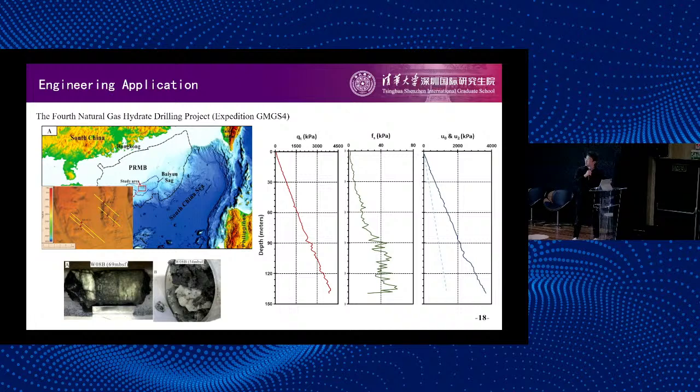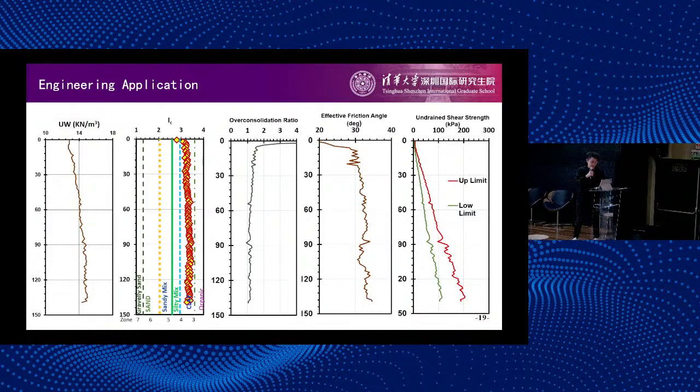Natural gas hydrate, which is the most promising clean energy source, is widely distributed in deep sea areas. The investigation sites of W118 and the recovered samples are shown, and the CPT data from the formation above the hydrate is displayed on the right. From the original CPT data, we derive the properties which give us insight into the geologic formations, which is essential for slope stability analysis and foundation design during the mining process.